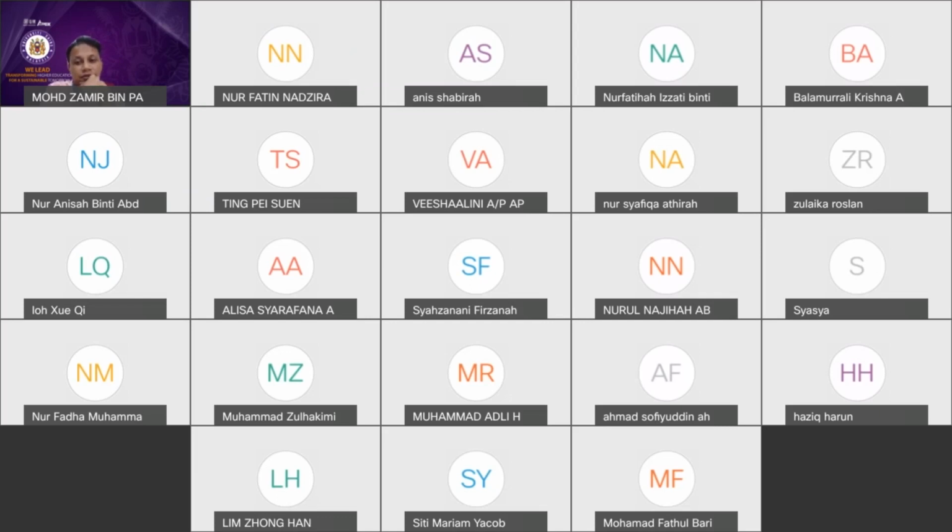Yes, right? So you are going to encounter different media which have different refractive indices, and if you plug in, you can replace silicon as N1 in that particular case, and the air at the back will be N2. So you are leaving silicon N1 into N2 air, your silicon is 3.9, your air is 1, so 3.9 minus 1 over 3.9 plus 1, squared.